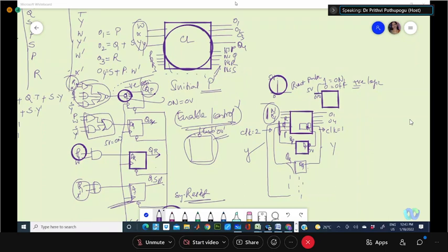And automatic closure of the door, say if you take, you need to have a sensor at the door point where it will count the number of people coming in one direction and going in the other direction. Say entering direction, you'll count up, and leaving direction, you'll count down. So you'll be using a counter there. Then controlling of the lights means you will be having the intensity adjustment based on the count of the people entering. That means you are relating the counter logic values with your light controlling.